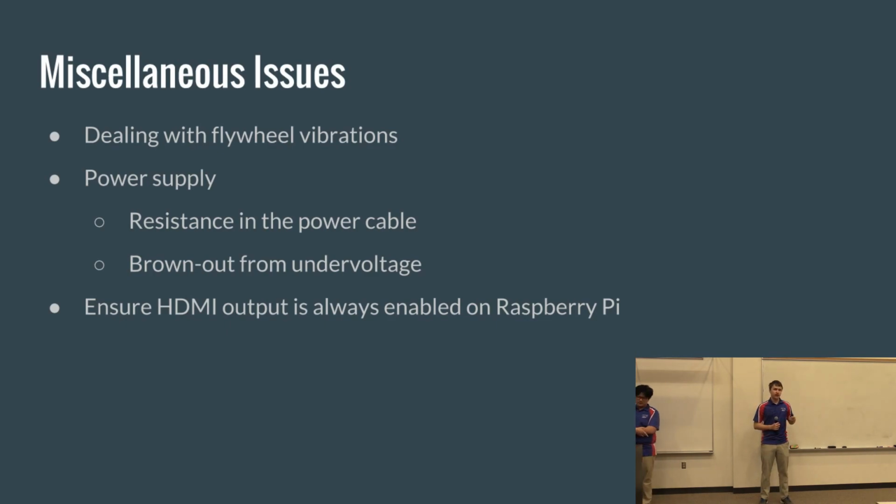When you're actually using one on a robot, you want to physically attach some cables to the Pi, like solder them in. There are pins on the Raspberry Pi that you can typically attach wires to in order to power it that way. That's much better for the robot because, especially in Stronghold, there's a lot of jostling, a lot of bumping, balls going where they shouldn't. If you hit your power cable and it gets unplugged because it's not a soldered-in connection, it's going to kill it, and then you'll be out for that match as far as vision processing.